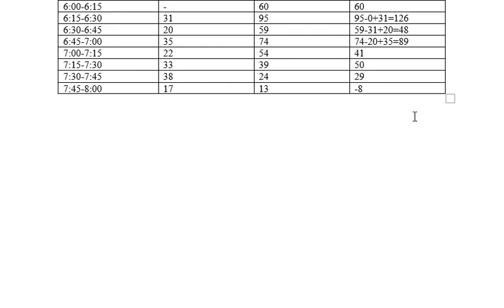Just to refresh what we did, so we wanted to calculate the number of vehicles arrived, okay, and the number of vehicles arrived was calculated from the number of vehicles which departed, and these vehicles cannot be equal to the number of vehicles arrived because some of them were already in the section from the previous queue. So I subtracted the vehicles which are already there, and then I added the number which was left in the queue after this time period. Okay, so this is how we calculate these numbers.